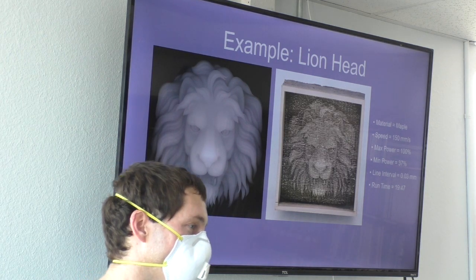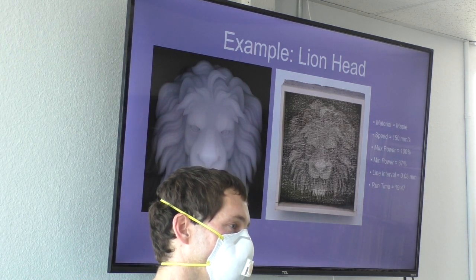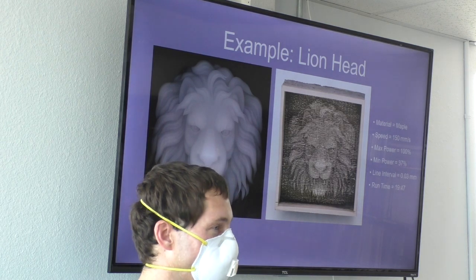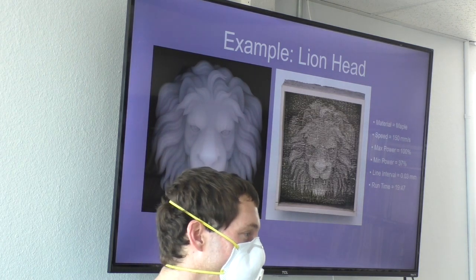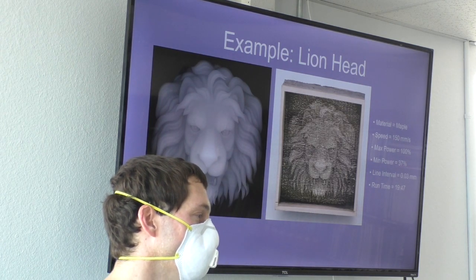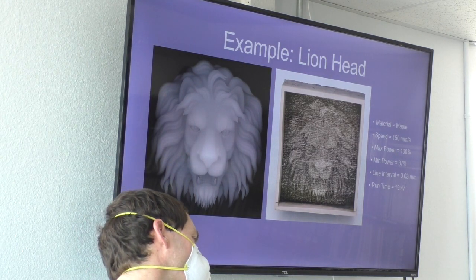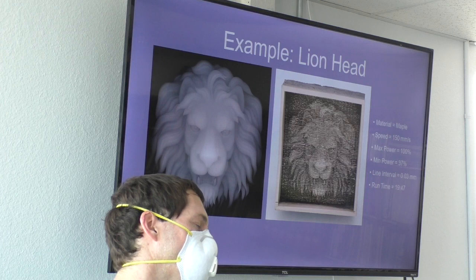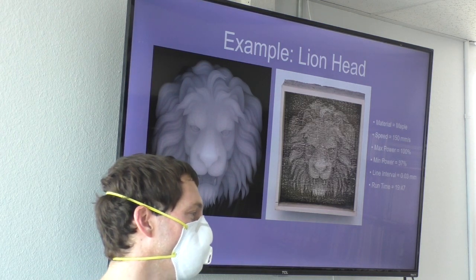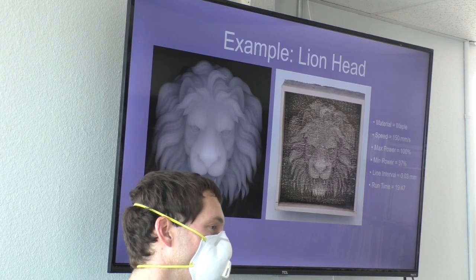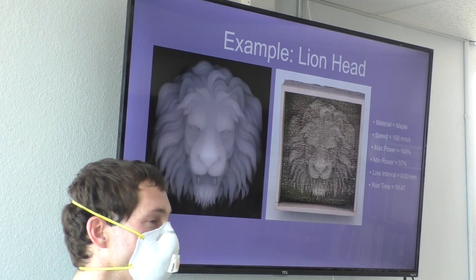Yeah, what a dramatic difference between this 3/4 inch and that other piece that we just passed through. Yeah, that one, I don't know exactly what the problem was. What were the settings you used to cut this piece? That one was 100% at 3 millimeters or 5, I can't remember. I think it's written on the bottom. I guarantee it's on the bottom somewhere. He always writes it.